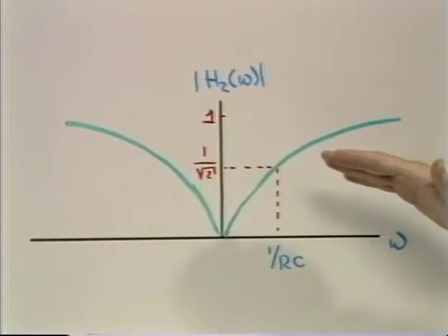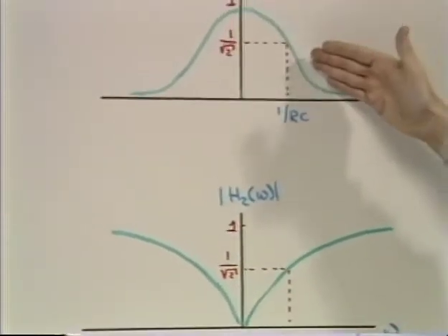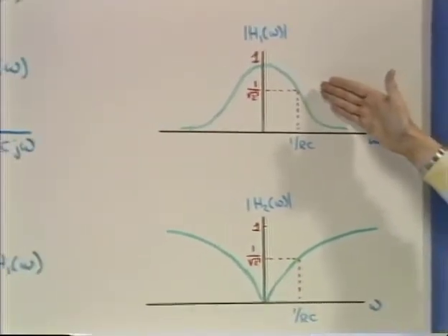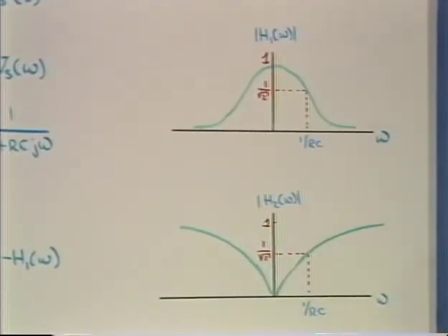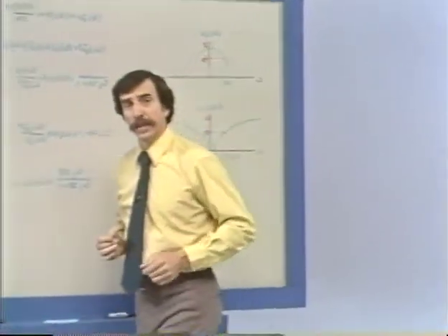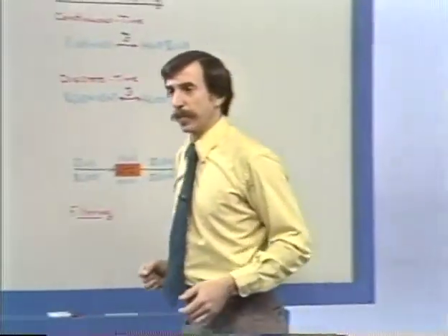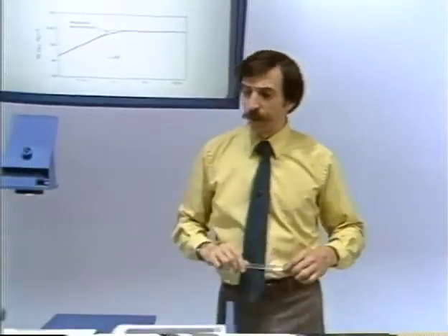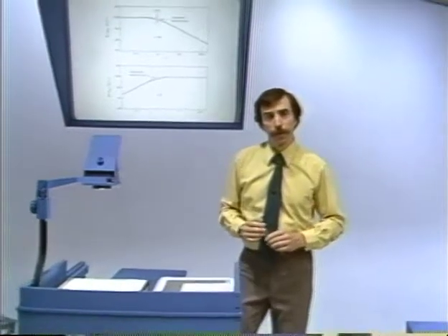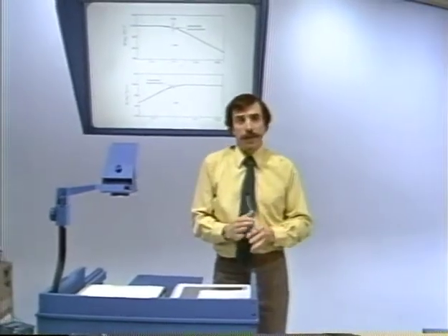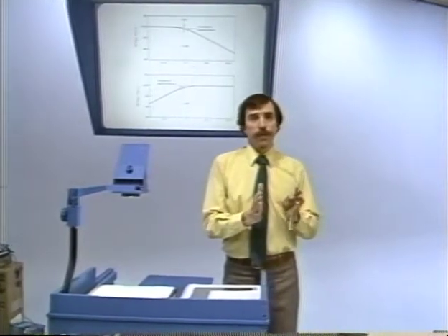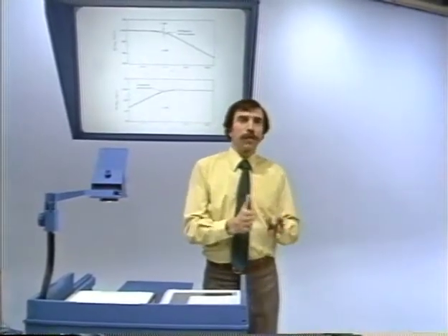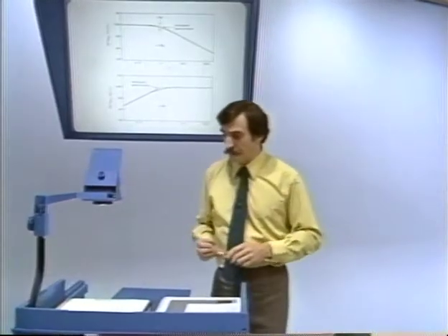So just comparing the two, we have a low-pass filter associated with the capacitor output, and a high-pass filter associated with the resistor output. Let's just quickly look at that example now, looking at a Bode plot instead of the linear scale that we showed before. And be aware, incidentally, of the fact that we can, of course, cascade several filters of this type and improve the characteristics.